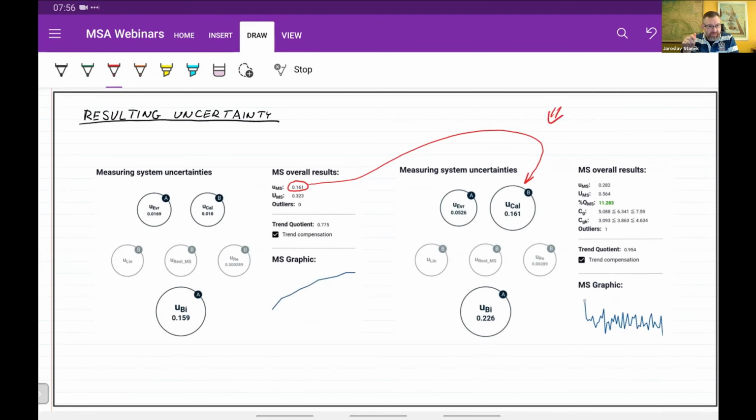And the component which is missing is the uncertainty of the calibration master, or the leakage master, that we have to test the repeatability on a reference. And we can do the repeatability, but we still don't know if the measuring device is biased. And to find that out, we use that orifice, we use that leakage master, but we need to know what is its uncertainty to plug it in.